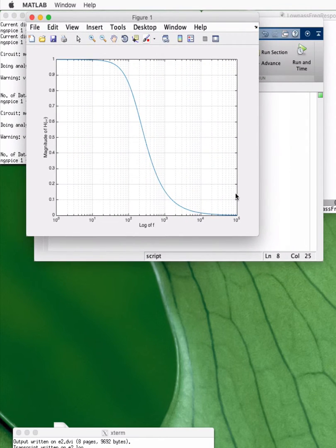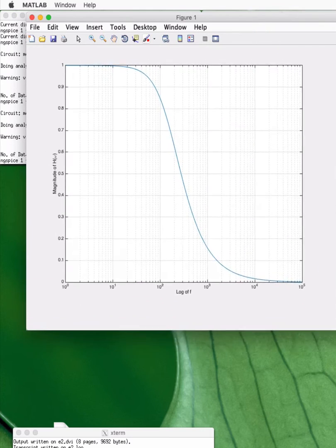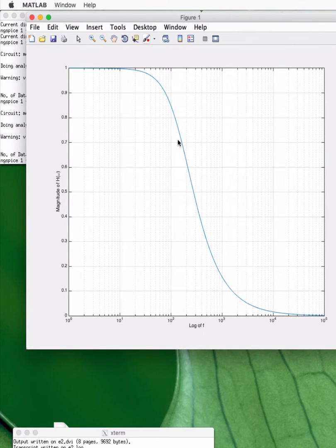and we look at our plot and we compare it to the SPICE, it's going to be exactly the same result. So for a value of 0.5, we're at about a cutoff frequency of 200 hertz, and we see the same kind of gradual drop. So the result is the same, but we're really fundamentally doing two different things.